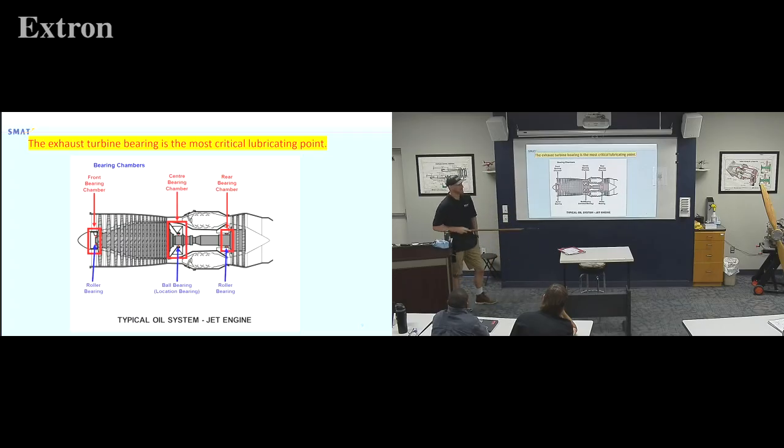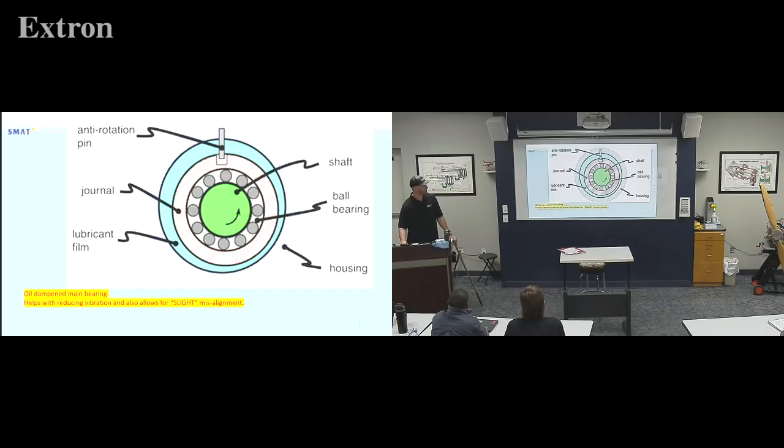So a lot of the forces on our turbine engines are actually, and this one you notice is a low bypass, it's pretty much a no bypass engine, felt in the different case sections and on the stator blades as well. So if your rotor blade is trying to push air backwards, your stator blade is acting opposite. But we'll get to that a little bit later. I just wanted to throw in that a lot of the bearings aren't actually holding the loads you might expect them to.